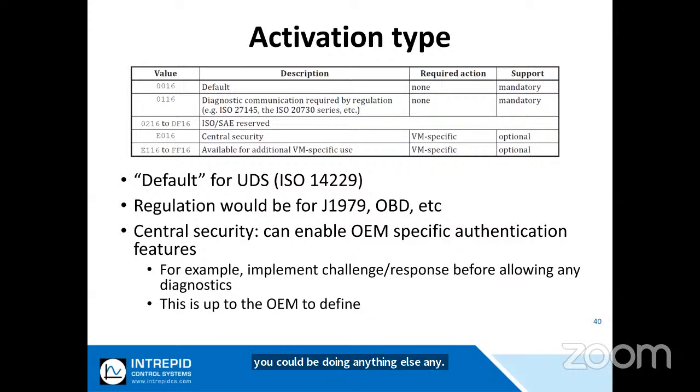The normal use is that that particular port is reserved only for DoIP. But I can see a time where you don't even bother with DoIP necessarily, and you start doing things like SOAD, which is socket adapter, talking directly to ECUs. But anyways, it's still a good point.